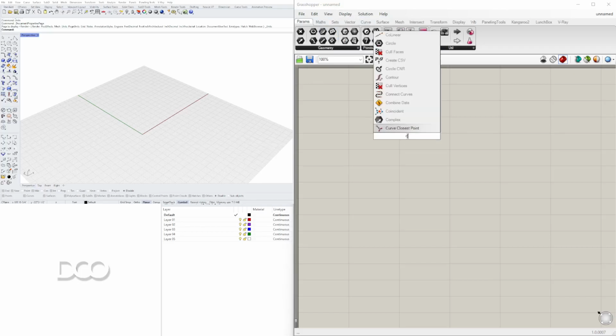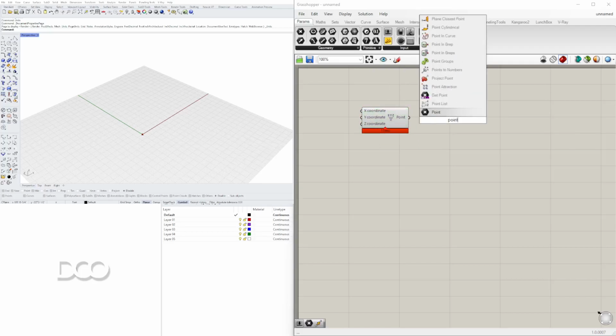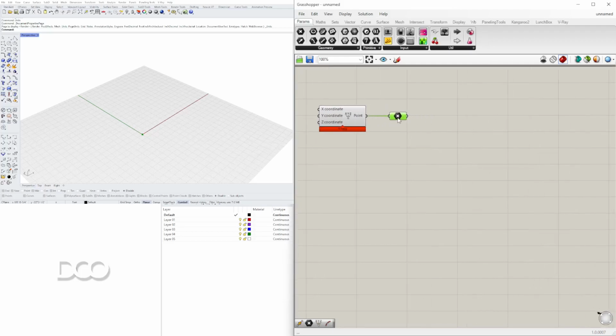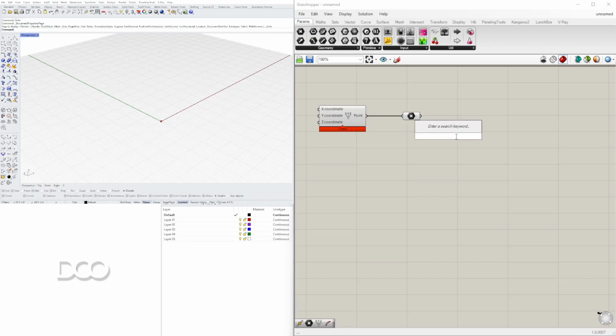We'll start by constructing a point. So we'll go here to construct point. Then we'll route that through a point component. This way we are able to change the location of where we have the design. So we'll go from this point. Now we'll be creating a reference plane that is in the X and Z direction. And this is how I visualize it, is I go here to the bottom left of my viewport and I have the X, Y, and Z here, and we see that X positive and Z positive. We'll go X, Z plane, and we'll plug the point into the origin.